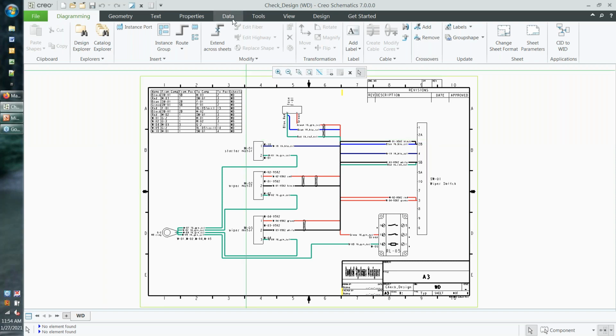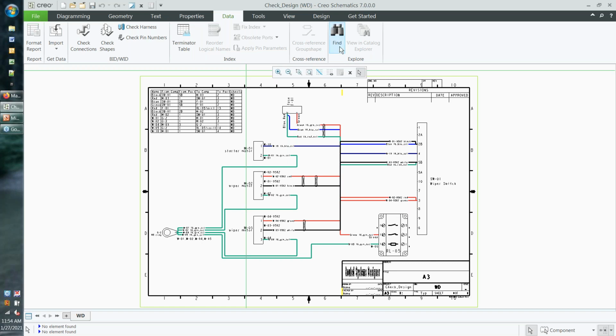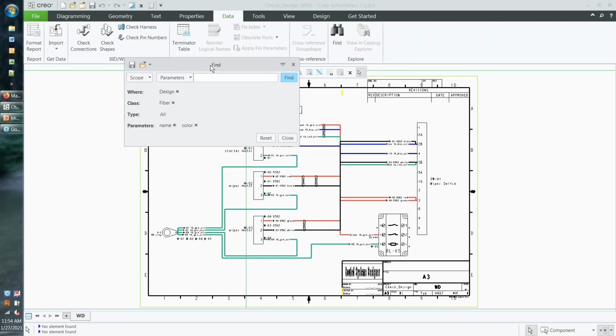Now, our Find tool is going to be found on the Data tab, inside of our Explore group. So inside of the Data tab in the Explore group is where we go get our typical PTC go-look-for-stuff binoculars. As I highlight the button so that the tooltip is displayed, Control F, the typical Windows hotkey for finding things, is in fact respected here, assuming you haven't done some other personal remapping in your system in some way. So we'll go ahead and light up our Find tool.